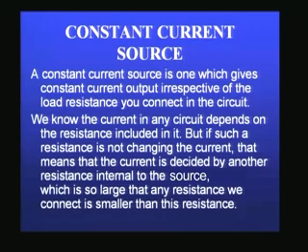So, you can immediately recognize that a constant current source should naturally be characterized by a very large internal resistance. So, how do I define a constant current source? A constant current source therefore can be looked at as something which has got a very large voltage source, very large value of voltage source, in series with a very large value of resistance. Together they can form a current source. The current value is decided by these two. For example, voltage divided by the internal resistance will be the current that you will get.